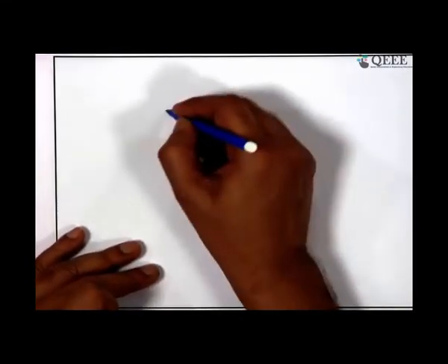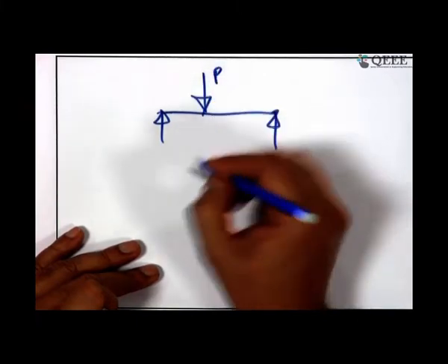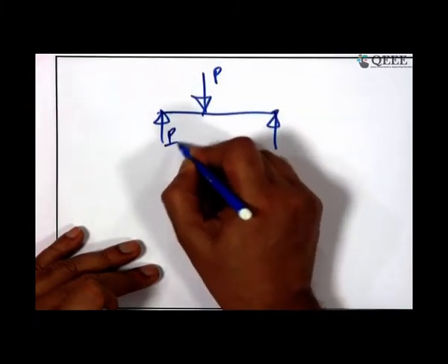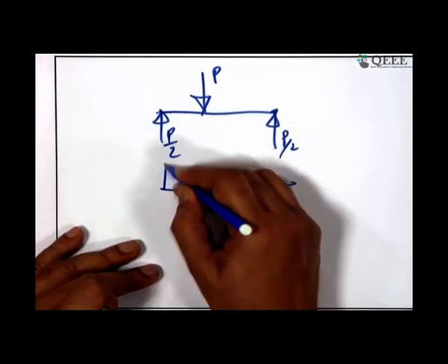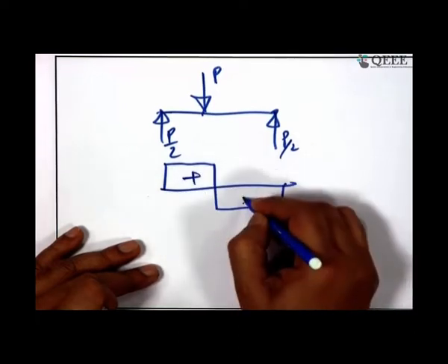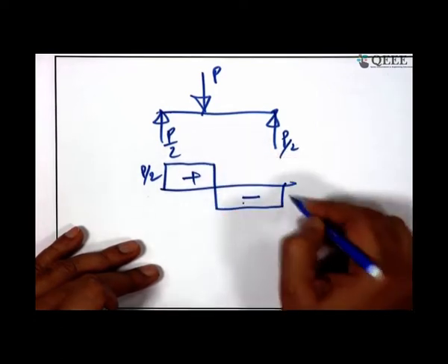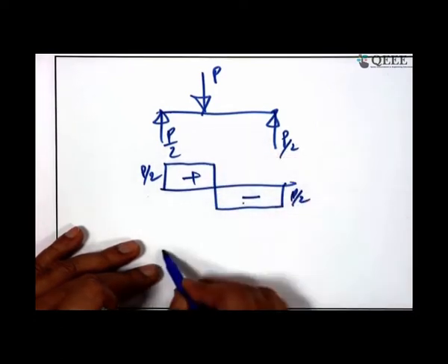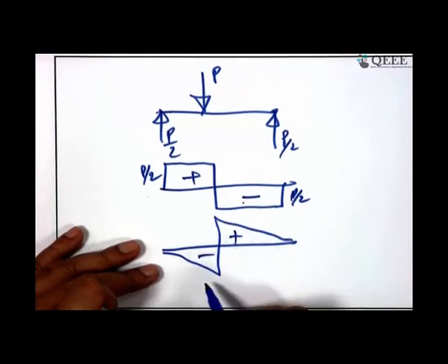So, you can recollect that this is the beam. Okay. So, you have a load here, and you have a reaction here, suppose P by 2, P by 2, I am putting the load. So, what is the shear force diagram according to our sign convention? It goes like this. It is the shear force diagram, positive shear and negative shear. So, it is P by 2, it is coming down by P, and then it is P by 2 negative. Now, what is the influence line diagram? You will find it like this, and not only that, it is negative, it is positive.